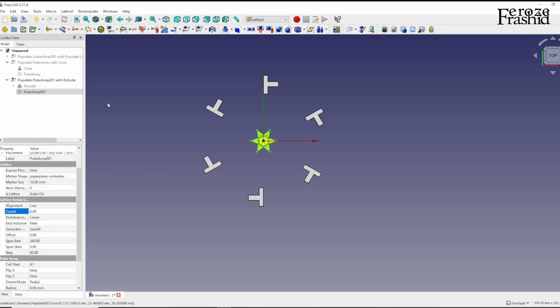So it looks like if an object is off the center and we made the radius 0 in polar array, the beginning object will be where the original object was, and then it will replicate beginning with the beginning object. So we make it 2, there is that. We make it 3, there. We make it 5. So there is always one object there. So that's one way to handle that. The radius could be the issue where the object is not on the center.